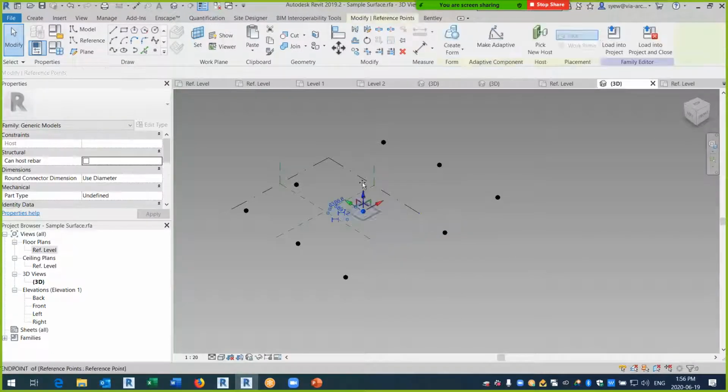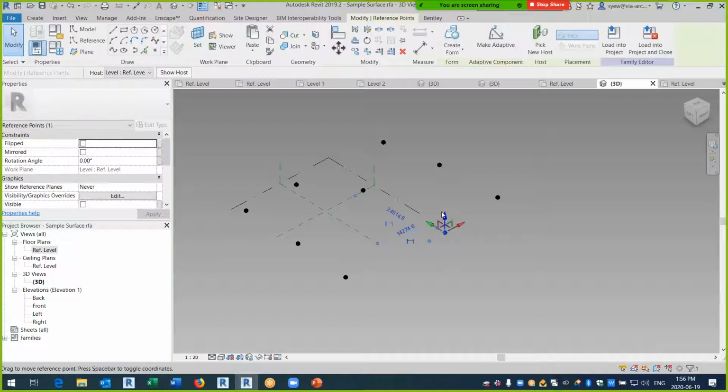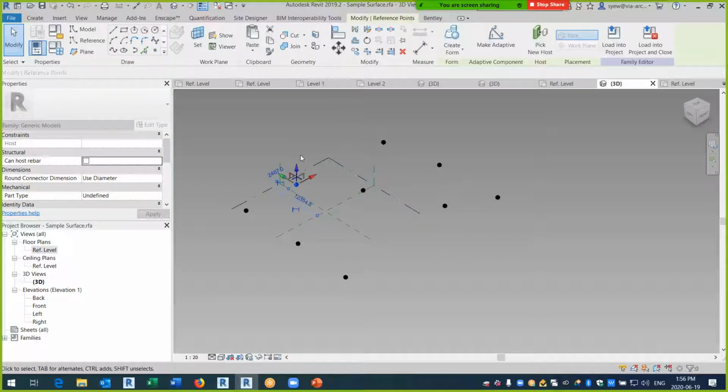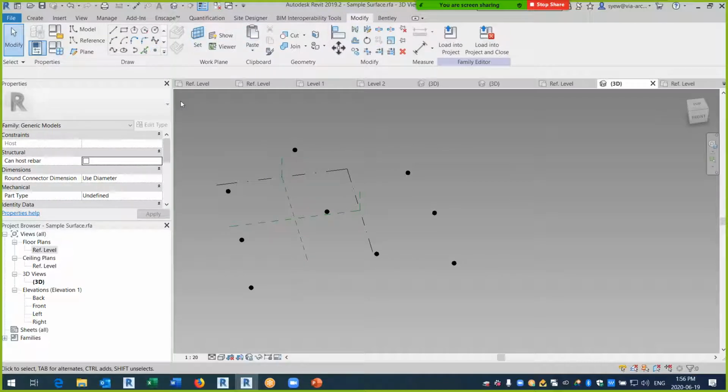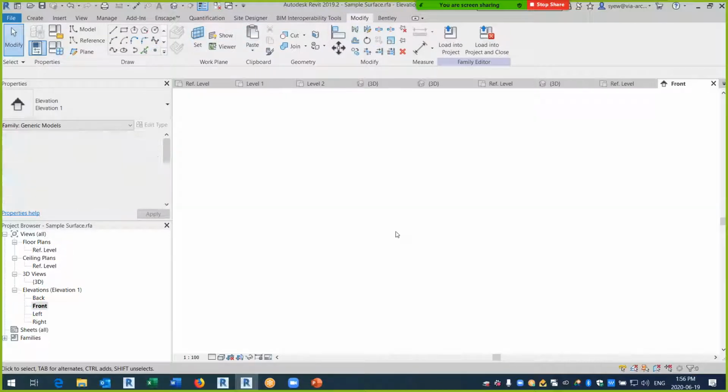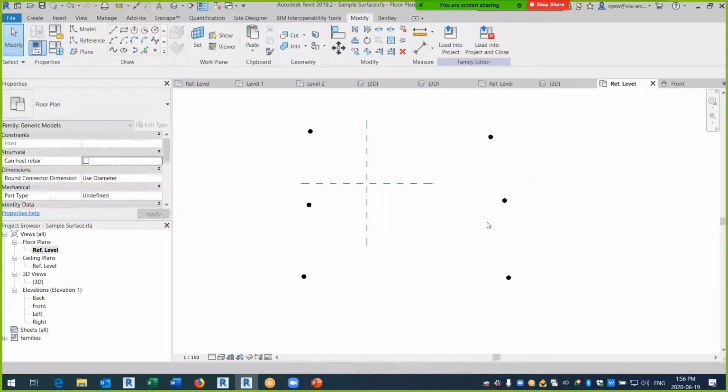So here, I'm just going to move my points around. The unfortunate thing about Revit is that once you put it in, you cannot change or add points. I wish you could, hopefully in the future, but in this particular case, it doesn't like to do it.